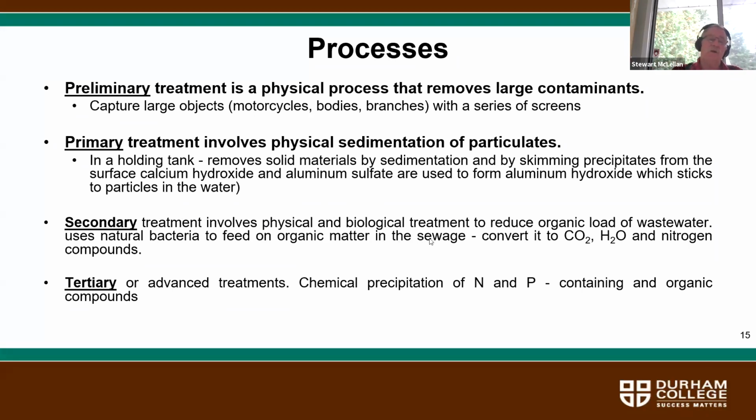of biological oxygen demand is important, because if you discharge wastewater with a high BOD content to a surface water body, it can be very damaging to any life forms that are in the water, because the bacteria will use the available oxygen to start breaking down these organic materials, and then that available oxygen is no longer available to other life forms, and you can have things like large scale fish die off because of oxygen deficiency in the water.